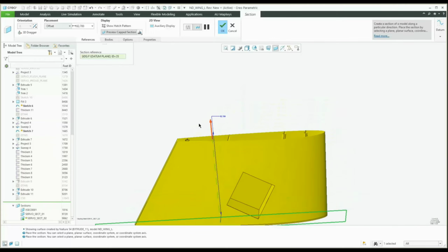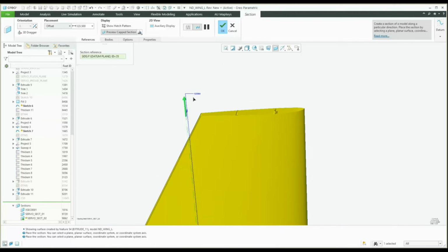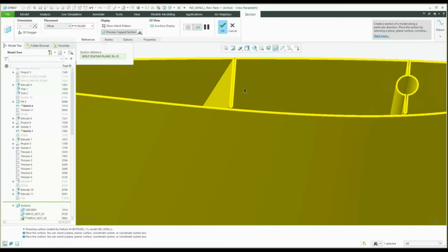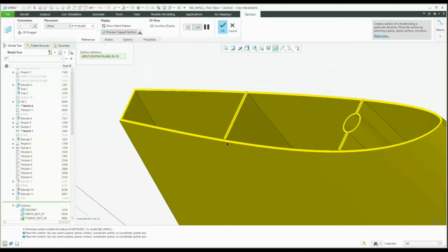Once you get the basics of this print technique, it is actually pretty simple to design parts this way. In the case of the wings, I designed them in surfaces to start, but ultimately converted the parts to solid by making the surfaces into shells that were of similar thickness to the print extrusion.